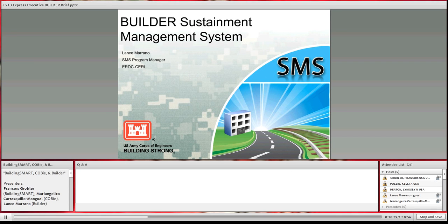It will provide you the information, and the software has to get that information and then use it. Otherwise you would be changing the spreadsheet manually, which I don't think is intended, nor will people do it that way. COBie is a specification of how information gets from one phase of the facility life cycle to the next, specifically from delivery to operations and maintenance. It's not intended to be used as a system for decision support.